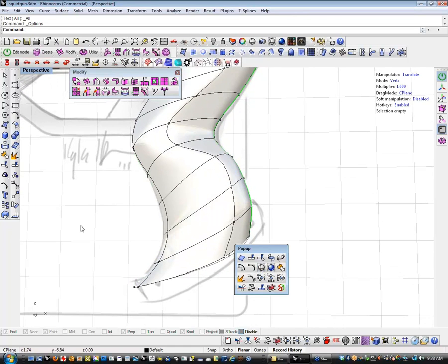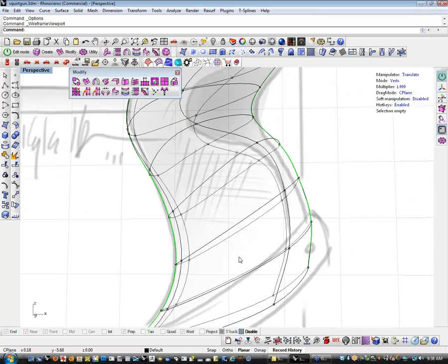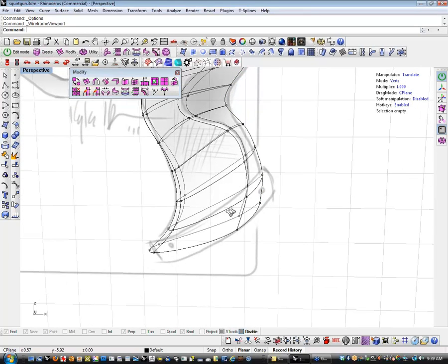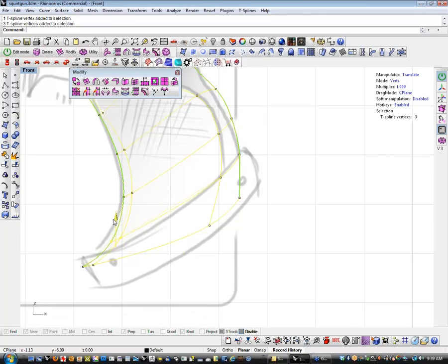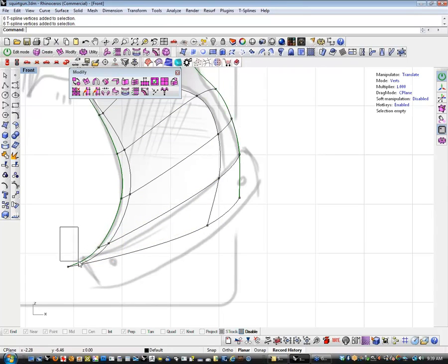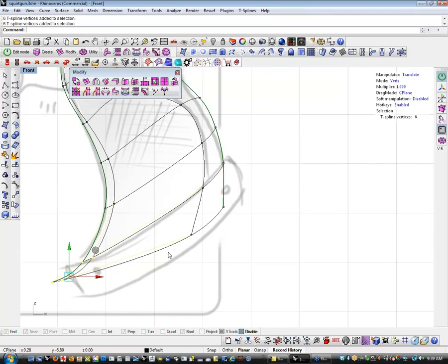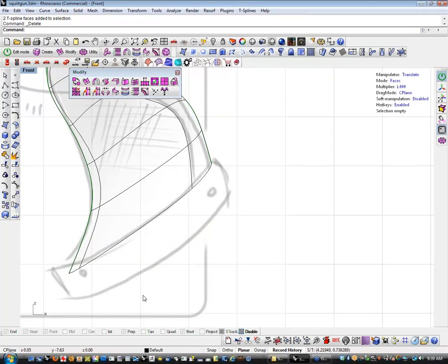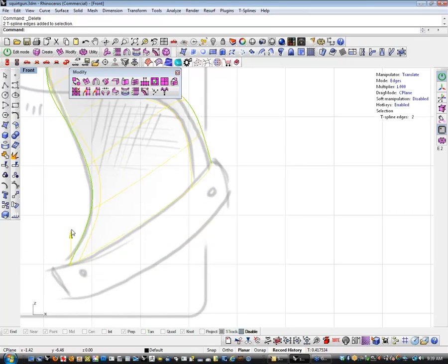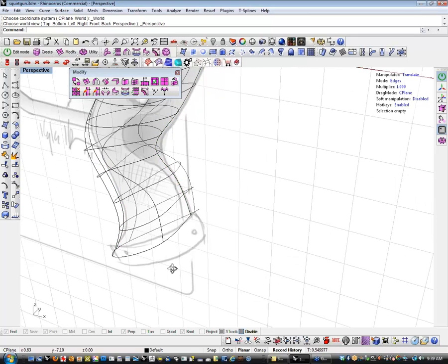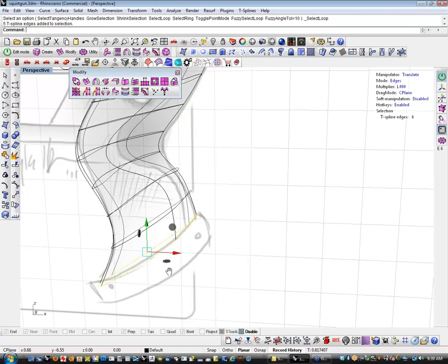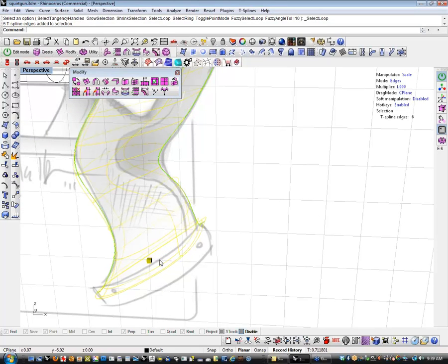All right. Now, let's unshade this and take a look at it. There's an opportunity here to use this isoparam as the basis for this hilt down here. I think that's the actual term for it. I'm not a gun guy, but I overshot this a little bit, so I'm just going to go ahead and grab these edges and delete them. And then I'm going to adjust this to match my line here. And then let's just Alt-drag and Alt-scale this hilt out to get what we need. So I'm going to pick this whole thing, I'm going to scale it, Alt-scale out, Alt-scale out.